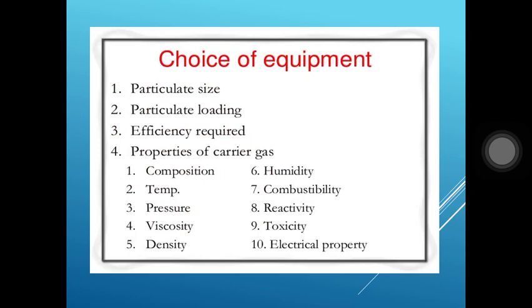Now, choice of equipment. The choice of equipment depends upon the particulate size, particulate loading, efficiency required, properties of gas carrying, for example, composition, temperature, pressure, viscosity, density, humidity, combustibility, reactivity, toxicity, and electrical property.